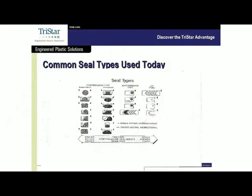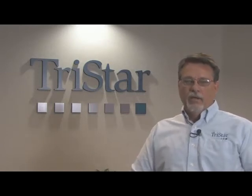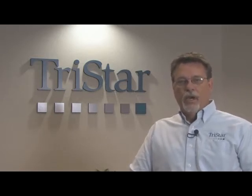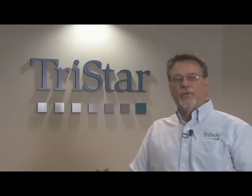O-rings typically will have an interference built into the design of the gland of 12 to 16% squeeze. So, you know, that by itself tells you that you've got a certain amount of stiction that you're going to have to overcome with that really tacky, sticky material. And so it makes sense to introduce something in between that sticky, tacky material that is not so sticky and tacky. And that's where the cap seals or slipper seals came into being. But if you look at those two columns, it's really a combination of elastomers and other plastics, in some cases even metals, to produce a classic compression or interference fit design.